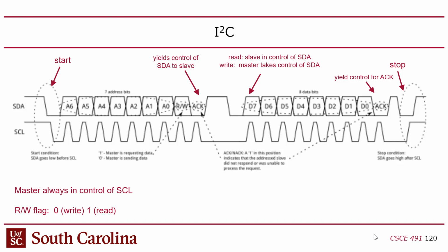So first of all, remember SPI used an edge-triggered clock, right? So we talked about how CPOL and CPHA were basically designed to have both sides agree on what edges of the clock to grab data, because they fundamentally were using flip-flops to read the data. You guys remember flip-flops? Hopefully you covered flip-flops in 211. Flip-flops use the edge of the clock, basically whenever the clock is changing from low to high or from high to low, depending on if it's rising edge or falling edge.